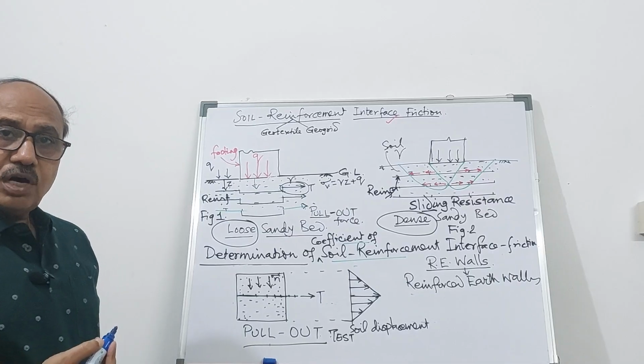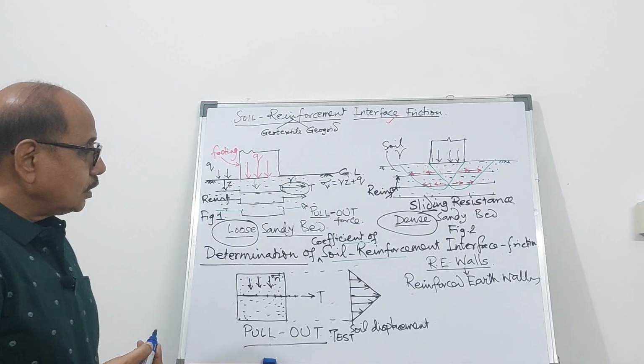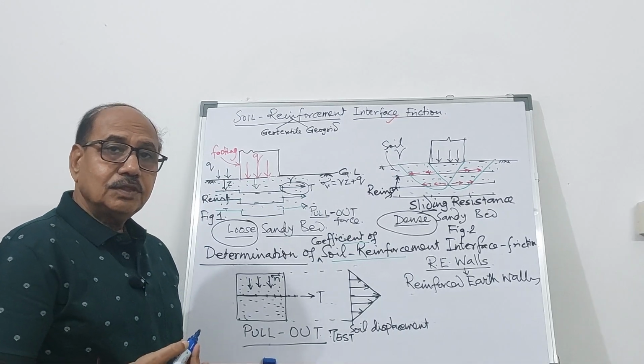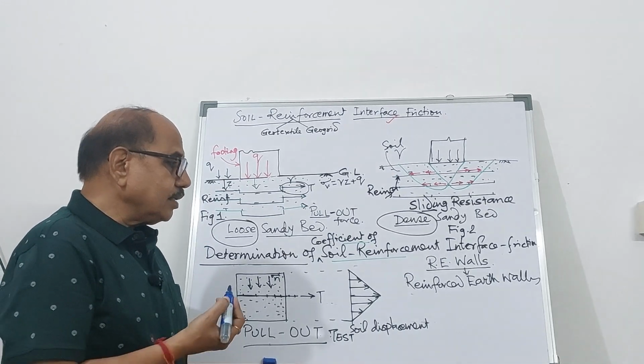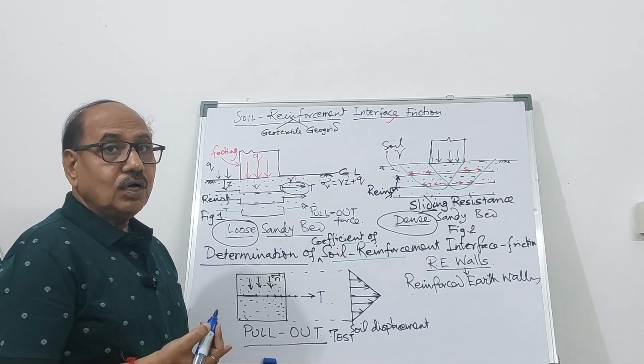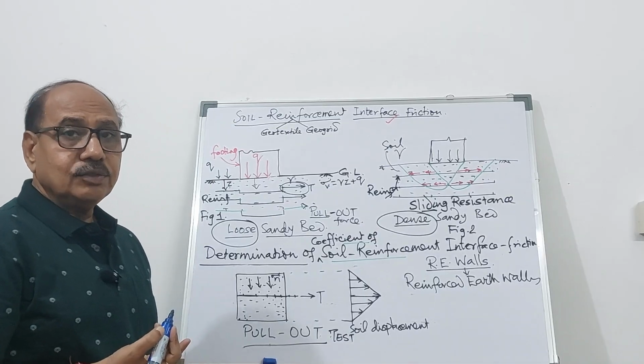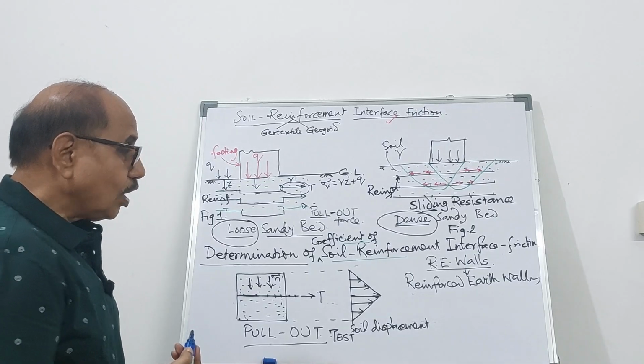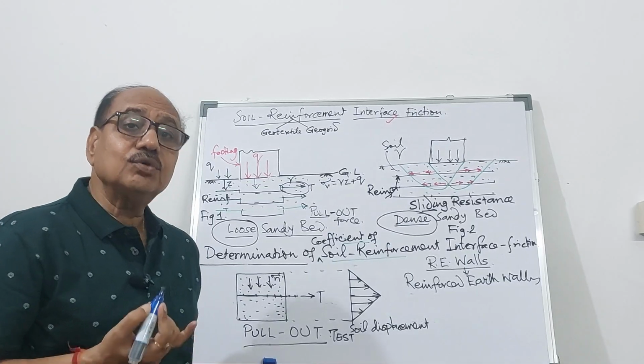It is a flexible wall, and under dynamic condition in seismic zone, these walls have performed very well compared to reinforced concrete wall. So RE walls have got their own advantages.